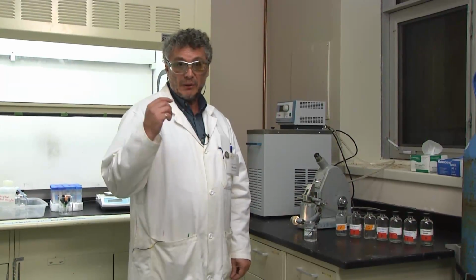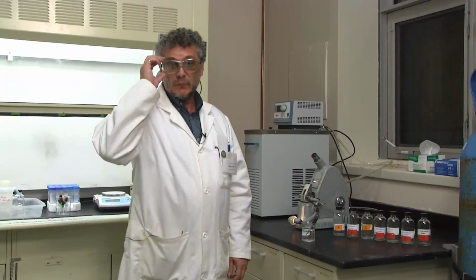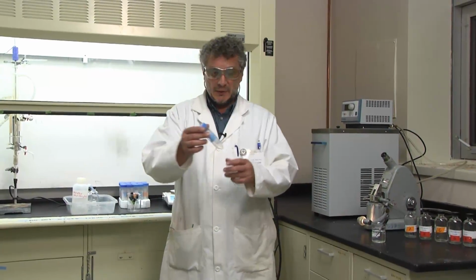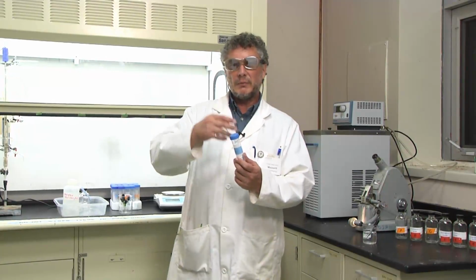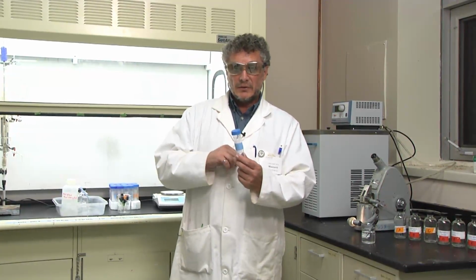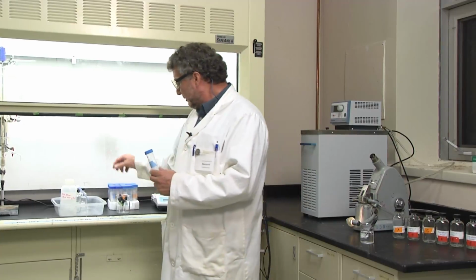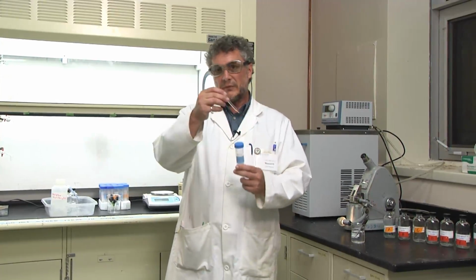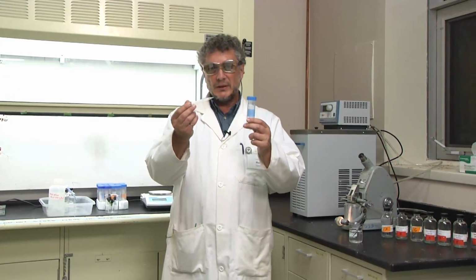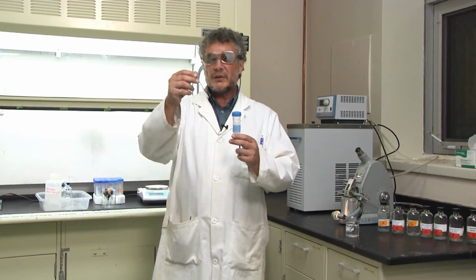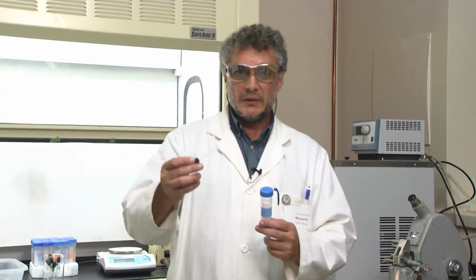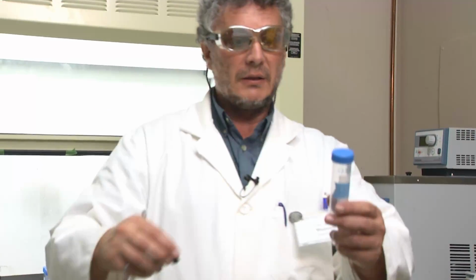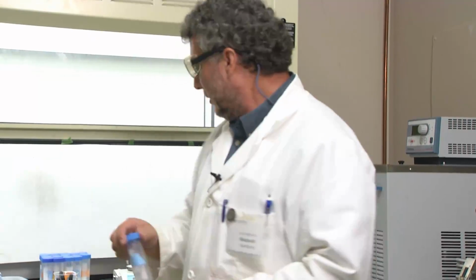When we take samples from the boiling point or vapor liquid equilibrium apparatus, one important thing will be to have them closed as soon as they're collected. Otherwise, some of your sample might evaporate and you might change the concentrations. So they will be closed, and you are going to use a dropper to take a drop out of it and place it in the refractometer. So these are going to be your 2 main tools. Now make sure the droppers are clean and dry, otherwise you contaminate the current sample with the previous one that you've taken. So this is how a dropper looks, right? And this is the type of tube that we are going to use to store the sample.